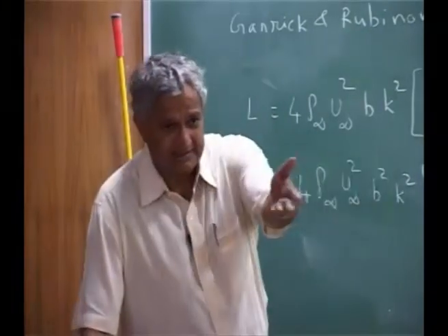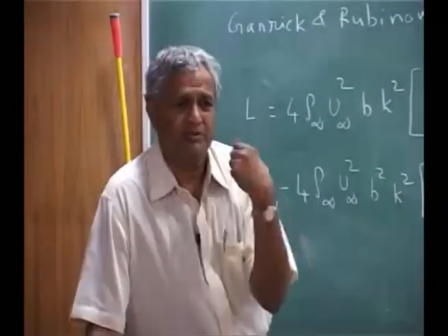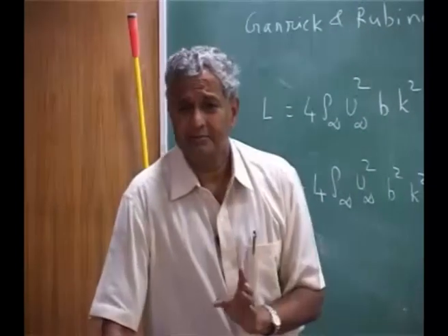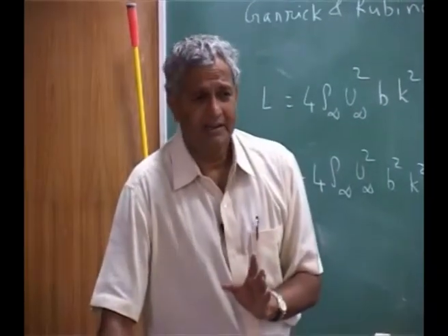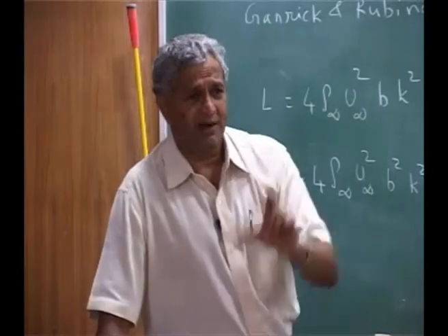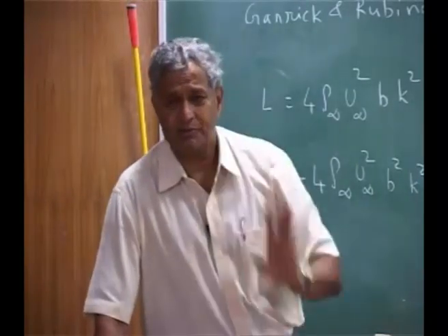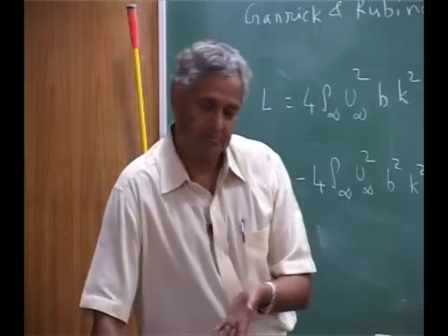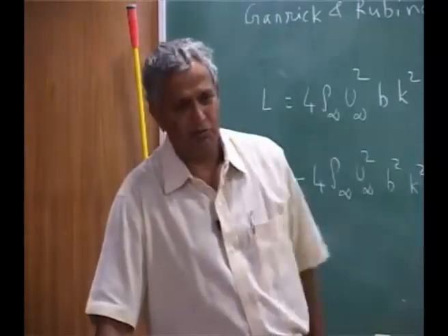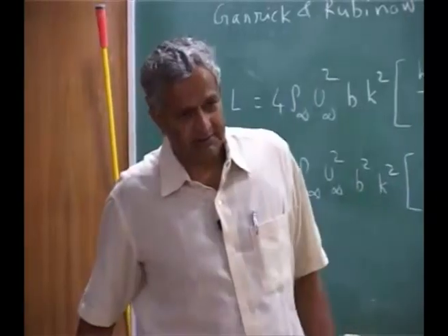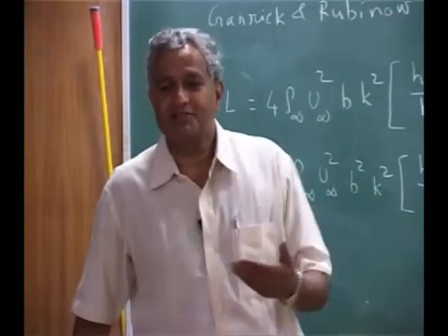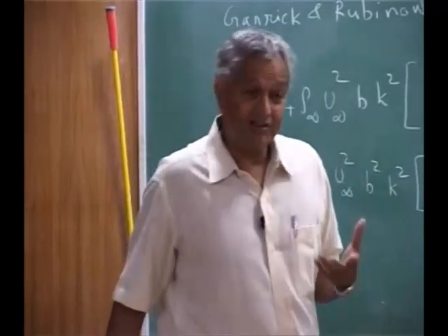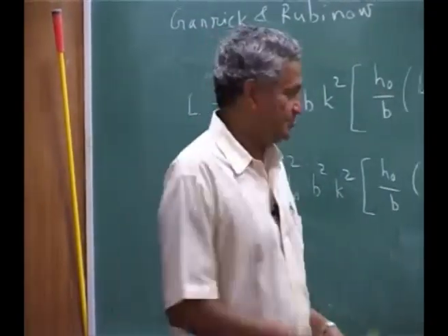You can do flutter analysis like what I did earlier, that is you assume that there is no phase difference, a very simplistic formulation I have assumed. Lift is every instant proportional to whatever is the angle of attack. If I use that, you will still get a result, but that is a very conservative analysis. This is a more sophisticated approach to solving the unsteady aerodynamics problem.